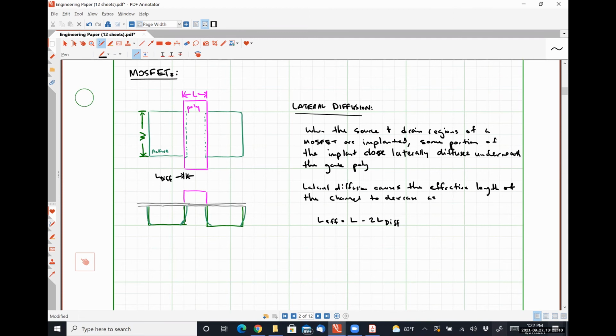So if we have a very abruptly defined place like this, where we have a very high concentration of, let's call this an NPN transistor or an NMOS transistor, a very high concentration of donor atoms abutted next to a significantly lesser concentration of donor atoms, or no donor atoms at all because we're in the P-type region, we should see that diffusion at a minimum wants to occur.